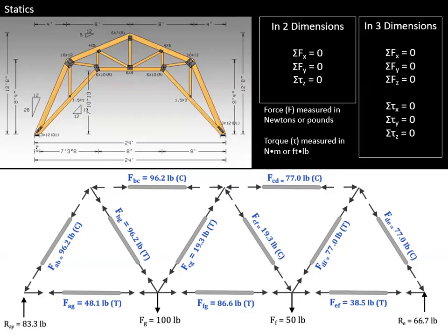Concrete has a lot of compressive strength, but almost no tensile strength. If you try to stretch concrete in a building situation, it'll just pop apart and it's no good for anything. But you can compress it. Now steel can go both ways. Steel you can compress or stretch. But steel's more expensive. So now you've got this trade-off.